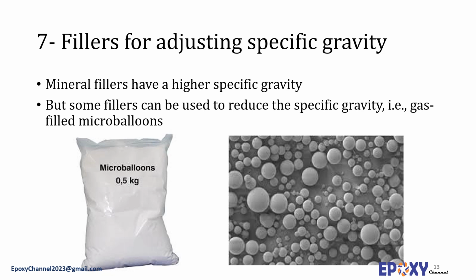The microballoon-filled epoxies, sometimes called synthetic foam adhesives, are often used in marine applications where low density and buoyancy are important criteria. Other low-density microballoons based on phenolic and other materials have been developed for use in epoxy adhesive formulations as well.